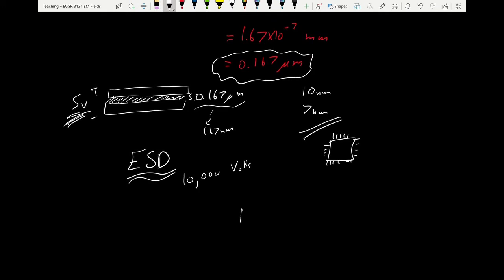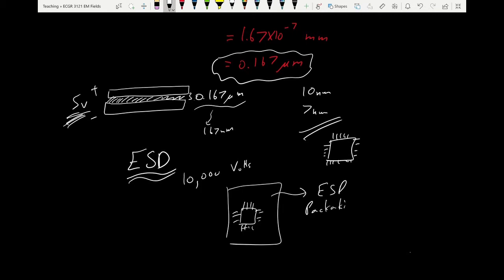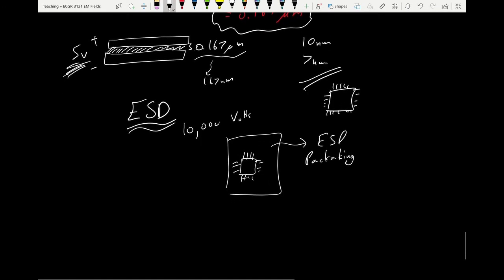And when you ship them, you notice that they are placed in protective ESD packaging. This is a special kind of conductive plastic packaging that allows the pins to discharge so no large charge accumulates that could kill those chips. And some chips have active limiting, actual circuitry inside the chip that limits the effects of ESD. So pure operational voltage is not the whole story for semiconductors.